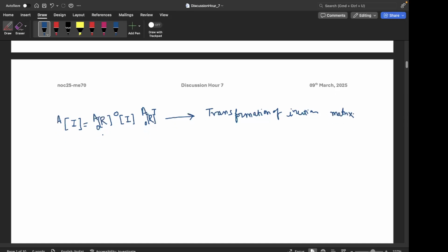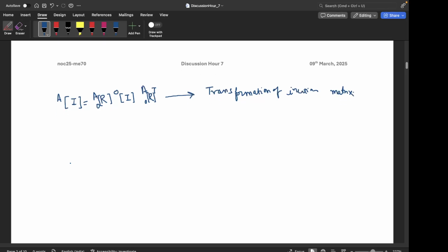So if there is a rigid body, I can express the inertia in its center of mass frame, or the world frame, or there is a special frame that is called the principal axis frame. When the inertia matrix is represented in the principal frame, the inertia matrix becomes diagonal. So for any body there exists a coordinate frame in which the inertia matrix can be expressed as a diagonal matrix, and this result also follows from a result of linear algebra, that a positive definite matrix is always diagonalizable.